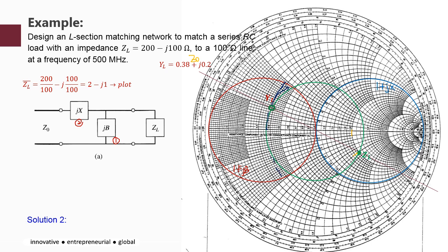Okay, move downwards there. We can call this solution 1 and solution 2. Let's take a look at the possible solutions. To match the admittance to 1 plus jB, there are two solutions. For the first one, we look at the shortest distance. So we move YL to position 1, which is up there. That's the shortest, so we name it YL1.